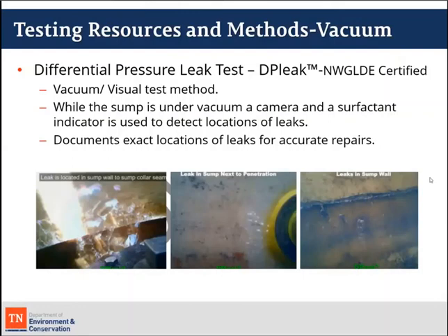Well, anything you know, that goes back to your sump preparation. Whenever you're in your normal release detection method, you want to make sure those valves are removed so that if you do have a leak, it can accumulate in the sump.